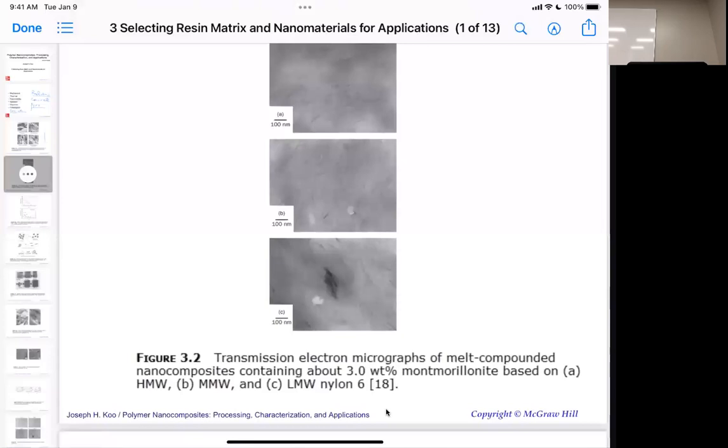So we had to figure out, okay, give us a mid, a low, and a high viscosity in the melt, and we saw which one worked. It turned out the mid grade worked best for our material. It had the best elongation properties, the best permeation. But you don't know until you try. But you have an opportunity to fix it if you only have one size. You say, okay, more shear, run it through two more times, break up this thing.